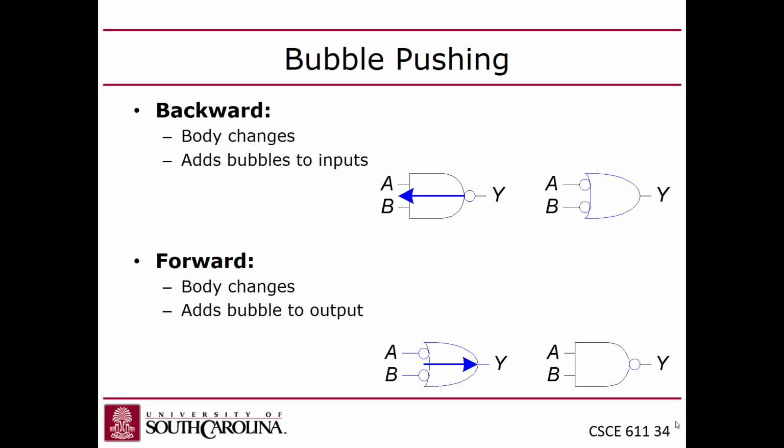If you're looking at an implementation of a circuit in an actual chip, they're going to be these negated gates. If you want to convert this to a form that is more conveniently expressible as a Boolean expression, you use this bubble pushing concept, which is where you basically just apply De Morgan's law backwards from the output towards the input.